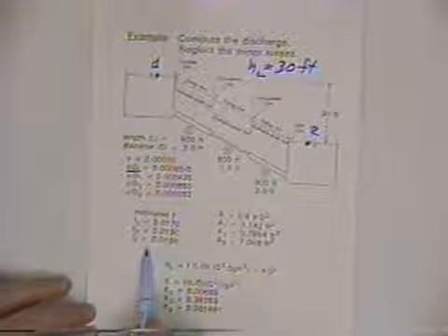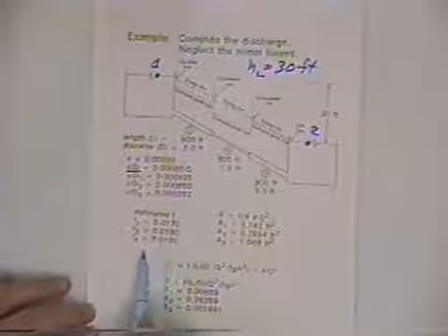So we need a relative roughness. For each of the pipes with the given diameters, we can compute a relative roughness, epsilon over D, which is one of the terms needed in the Moody diagram to get the f for the Darcy-Weisbach equation. Same story as before. The only difference is there are three pipes now. We'll estimate the friction factors without the Reynolds numbers and then check them. And here's the Darcy-Weisbach equation again, the same equation we've used already.